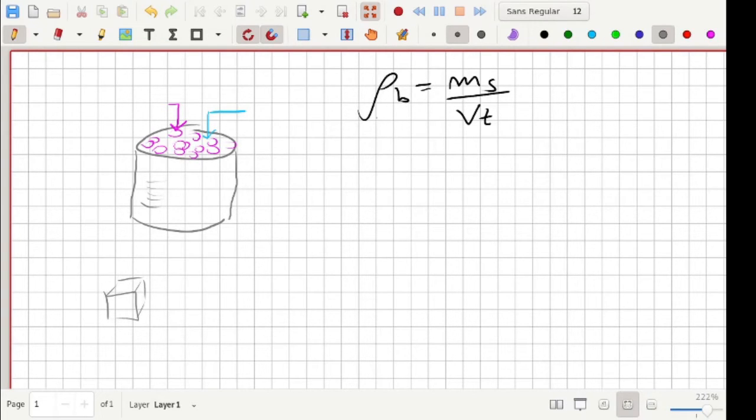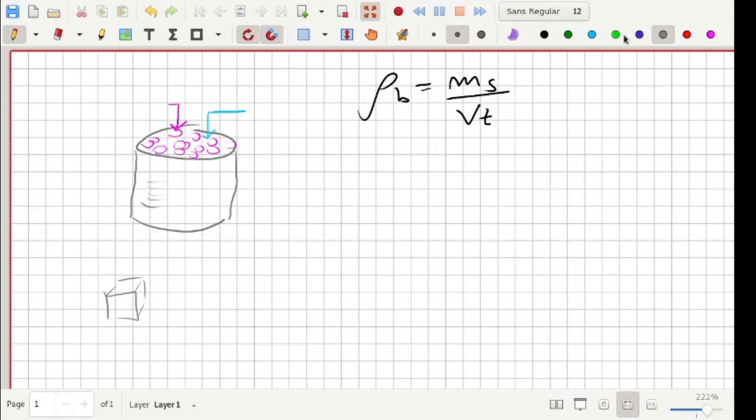Usually when we're talking about bulk density, we're talking about the dry bulk density. So we dry this sample, usually in an oven at around 105 Celsius, to extract the water. So you're left only with residual water tightly adsorbed to the solid surface. But it is also possible to calculate the wet bulk density, which would consider the fluid inside this material. What is the water content? The water content is usually represented, at least in soil science and sometimes in hydrogeology, by the Greek letter theta.